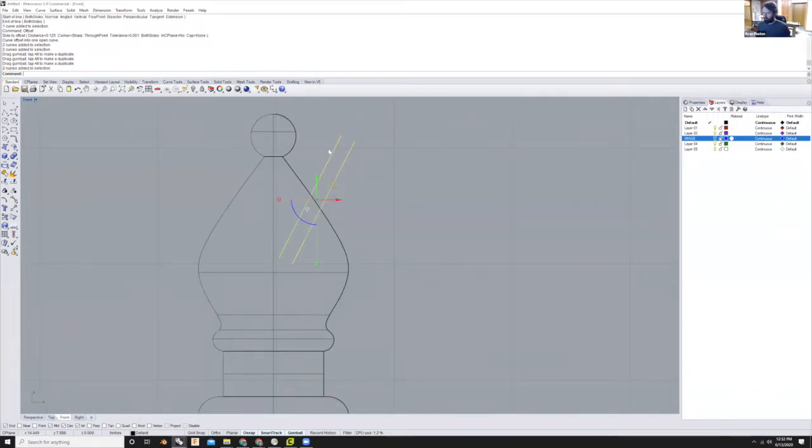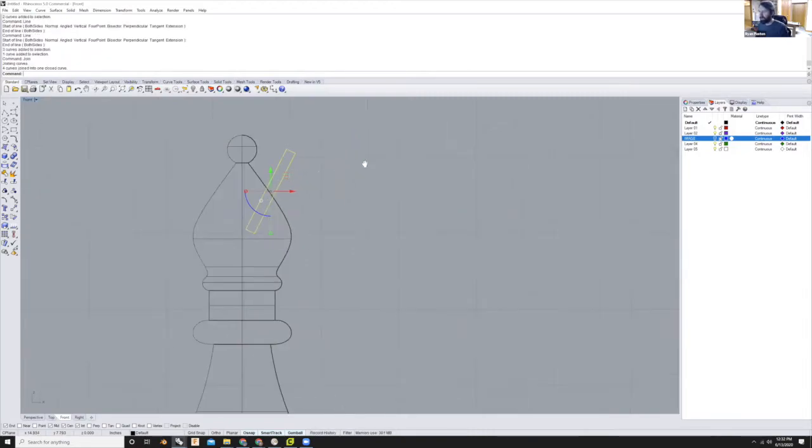And like we've been doing all along, I want to turn this into a closed curve. So I'm going to create 2 more line segments, one here, enter. And I don't have to type line again. I can just hit enter, and it will re-perform that same command. So now I have 4 lines, and I want to join them together. So I've joined these together.